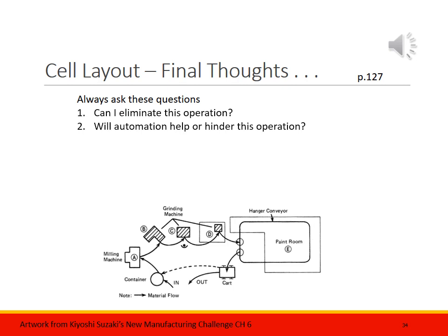All I'm saying is be cognizant of the fact that operations that are automated aren't always the right choice. You want to ask yourselves, too, when you look at these operations, are they really separate operations? We laid all the steps out, and we had the diagram and the PQPR, but you have to ask the more fundamental question, right? Process D and E, machining operation 1 and machining operation 2. One's running on a lathe and one's running on a mill. Okay, but maybe they could both run in the mill.